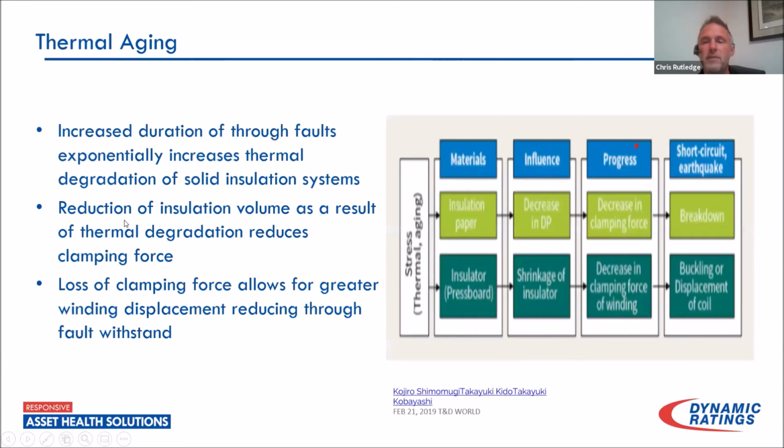So the thermal aging process, how does this affect our transformer in reality? As I said, there's 2 portions. We have the current portion, which is I squared, which is definitely our mechanical mover of that core and coil assembly. And then we have duration. Duration attributes largely to the actual thermal degradation we see on that event.